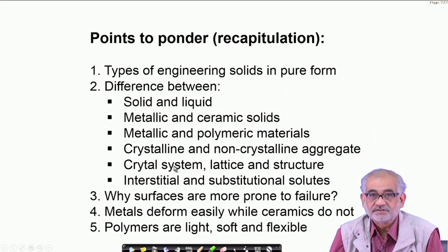We discussed the nuances of point lattices, then unit cell lattice parameters, crystal lattices or Bravais lattices, 14 of them, and then the infinite number of crystal structures that can eventually arise out of these. But we must not forget that no matter how complex a crystal structure is, if it is crystalline, then it must be related to one of those 14 Bravais lattices.